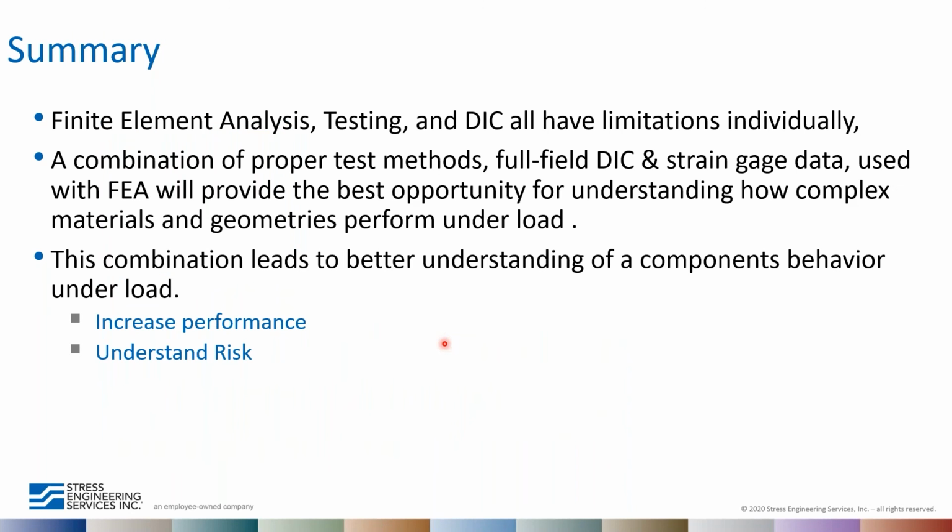And so finite element analysis and testing and DIC all have limitations individually. At Stress, I feel like a combination of proper testing methods, using the full field digital image correlation and strain gauge data, along with FEA, can provide the best opportunity for understanding how complex materials or geometries perform under load.